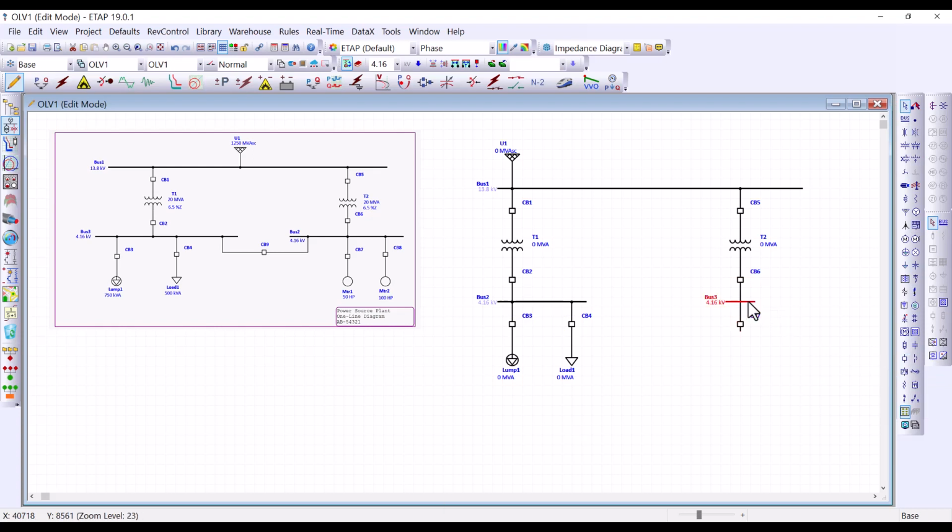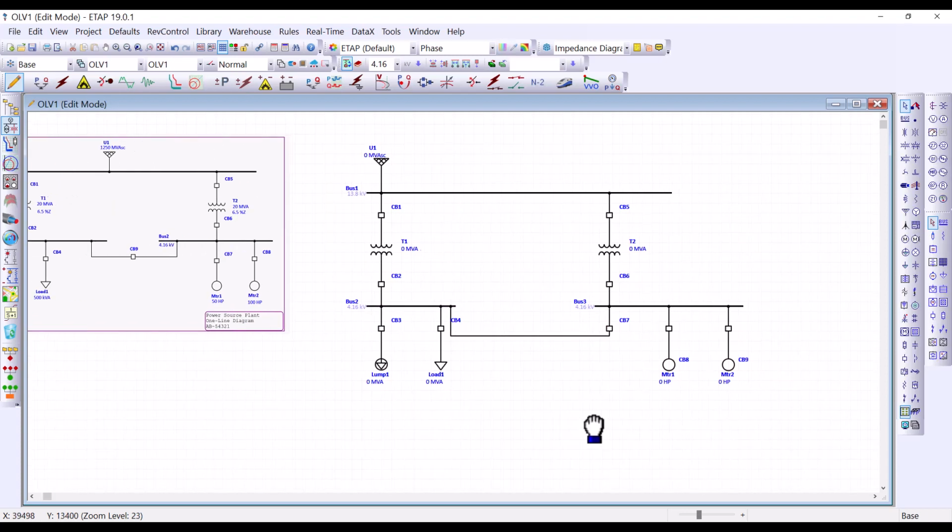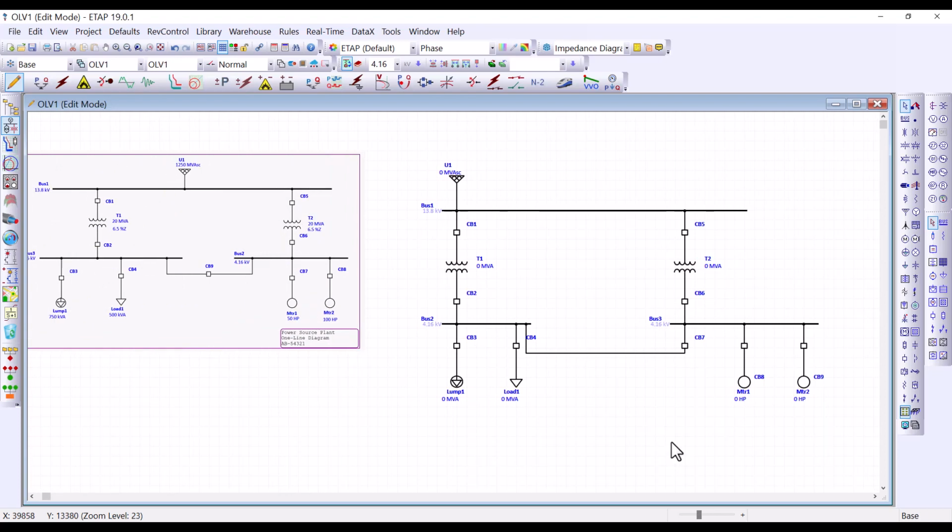click on the bus so I can move to the right, and add 2 induction motors. From here I am going to highlight the 2 induction motors, and the auto build allows you to just select a group of components and add your breakers on top. Now I have the cross tie, I'm just going to put it here. And that's really how you build your one-line diagram using the auto build.